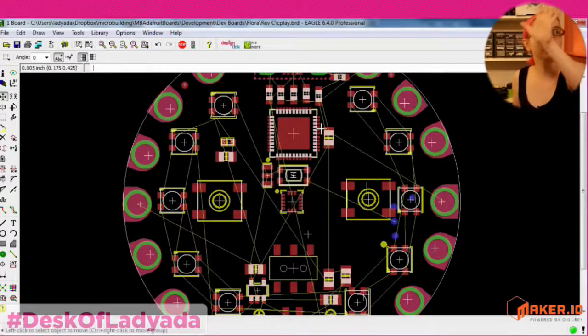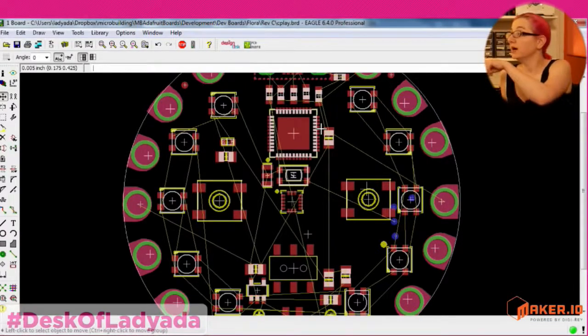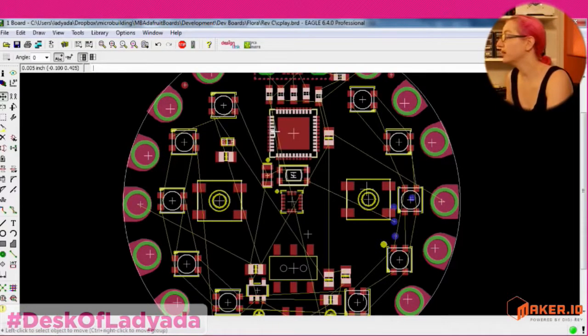What I usually do is get all the components in the right location, because it doesn't really matter what digital I/O or analog pin you use. Very few pins are super special purpose. A couple of them are, but most of them aren't. Even things like SPI, you can bit bang SPI. So having all the components placed where you want them on the circuit board, and then routing the traces and picking the closest pin. So of course, when I pick the analog pin to go to this phototransistor, I'm going to pick one from over here, not from over here, right? Because it'll just make my life a lot easier.